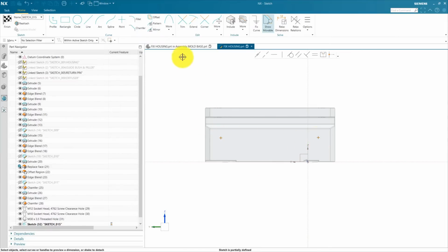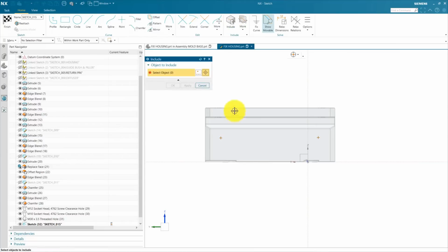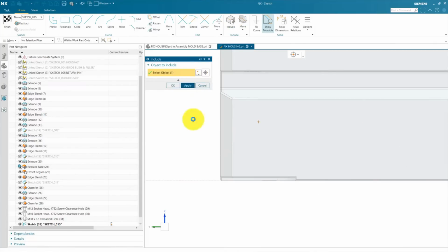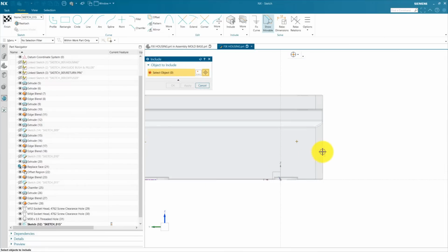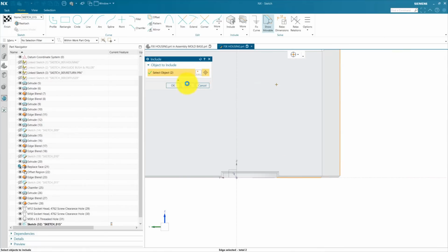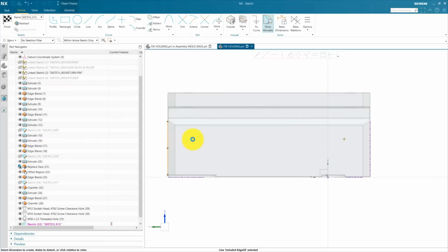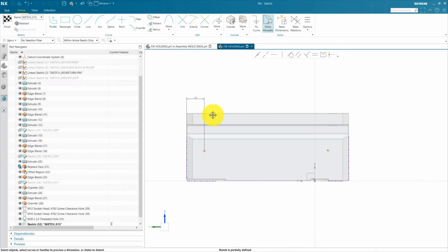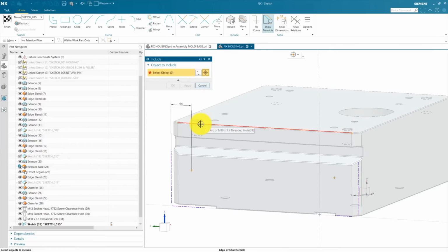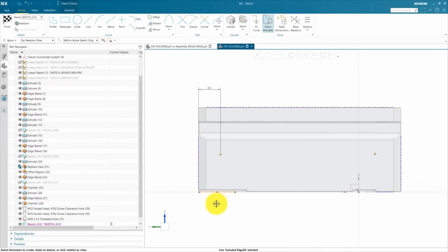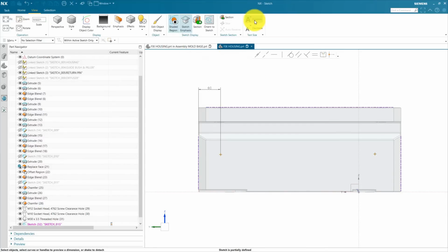First we place some points. Now we are going to define dimensions. From this we are going to add include curve. We can take reference from the outer. So define the dimension from this to this. Use 60 mm. We are going to take reference from this bottom face. So include this edge. Okay, and delete this include. We don't need this.